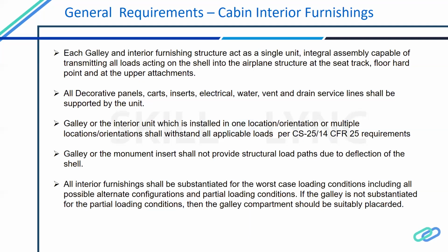And in some cases, the galley and interior monuments are subjected to abuse loads. Abuse loads are nothing but the loads that any passenger or any crew member can exert on the galley.